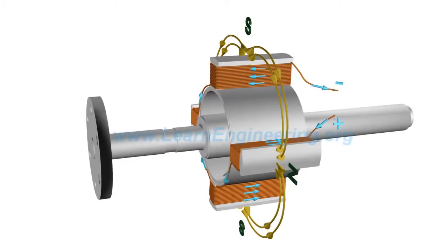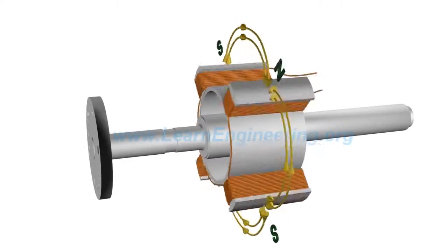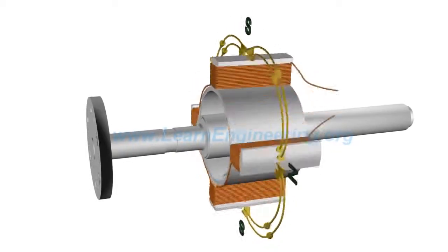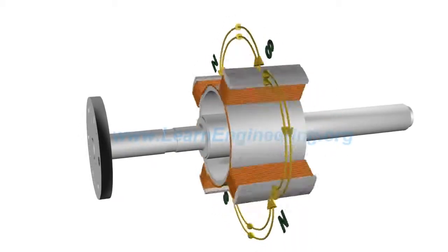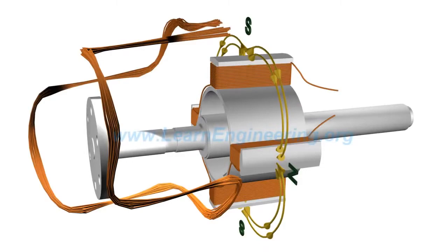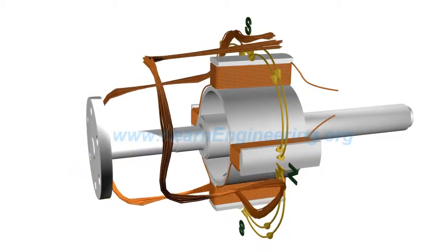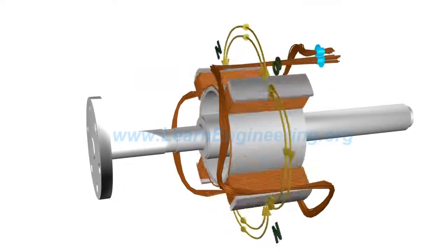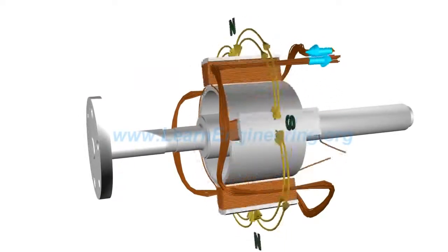The rotor is made to rotate by a prime mover. This makes the rotor flux also rotate along with it, at the same speed. Such revolving magnetic flux now intersects the armature coils, which are fitted around the rotor. This will generate an alternating EMF across the winding.